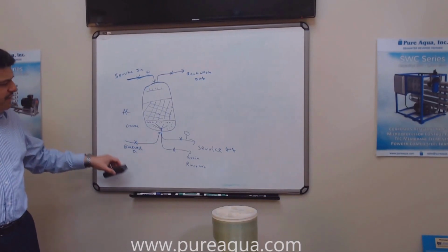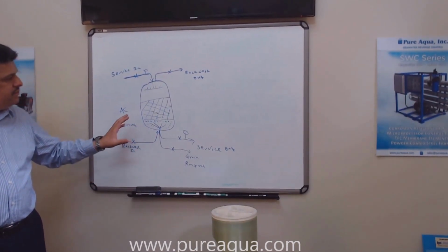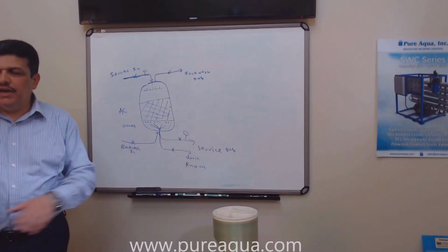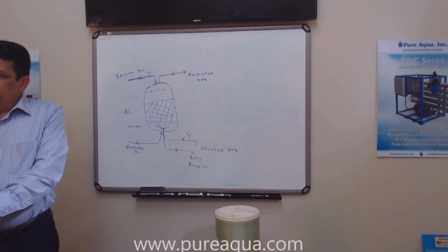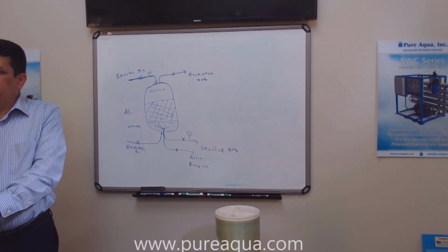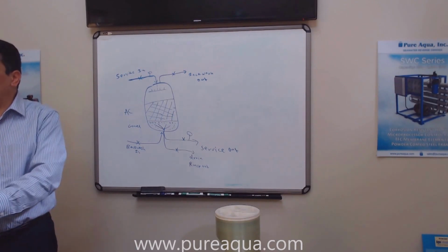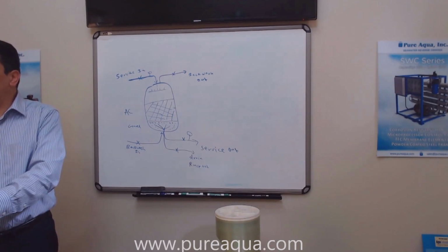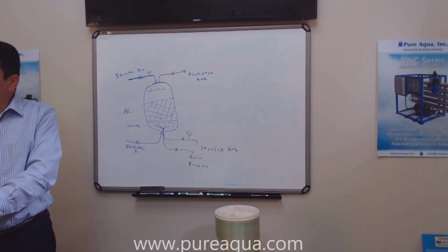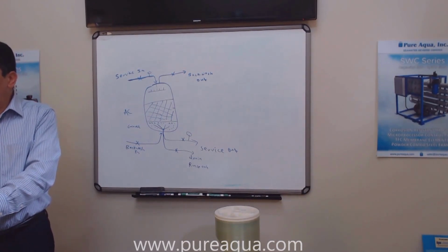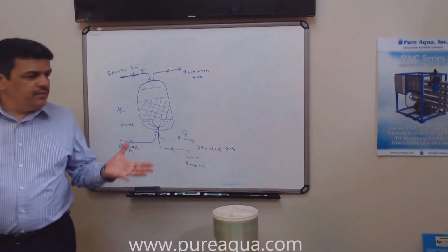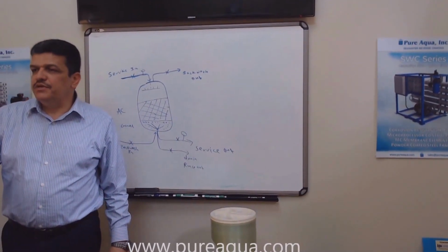So the benefits of having an activated carbon, like general coconut and good ones: it takes organics, takes the chlorine, takes bad odors, smells, and you name it. Whatever is in the water, it's a very good media to get rid of those things. Do we need to backwash the carbon filter? Yes, you do. But you don't need to do it like the media filter. Again, the carbon filter is not designed to remove suspended solids.